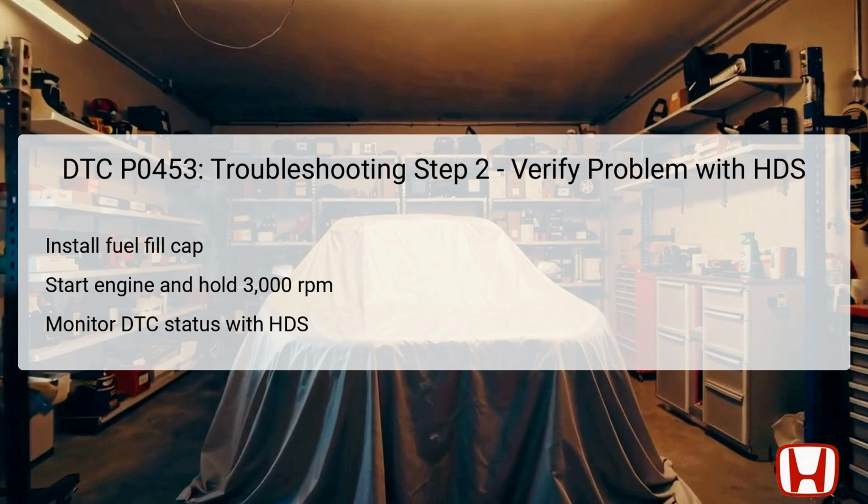During this test, monitor the DTC status via HDS, specifically checking if the P0453 code is indicated as failed, passed, or not completed. If the DTC status is failed, it confirms a duplicated failure, prompting further investigation. If it reports passed or intermittent, it suggests the fault may be transient or intermittent, guiding the next steps and perhaps further monitoring. Accurate observation ensures proper diagnosis and prevents unnecessary component replacements.